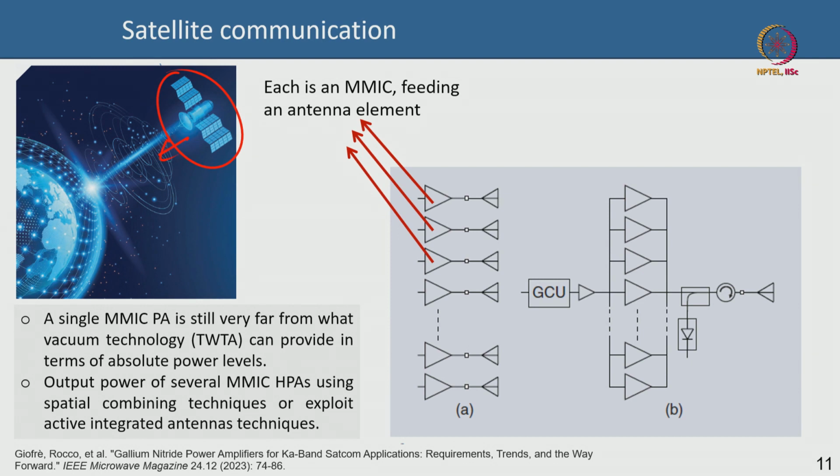So you see there are many techniques to have this worked out, because historically and even today such high powers of a few hundred watts or a few tens of watts at very high frequency, when I say very high frequency, maybe Ka band is say 28 to 40 gigahertz, that is a really high frequency. At that frequency if you need hundreds of watts or maybe say 50 watt or 100 watt, it is almost improbable that a semiconductor technology will give you that, really.